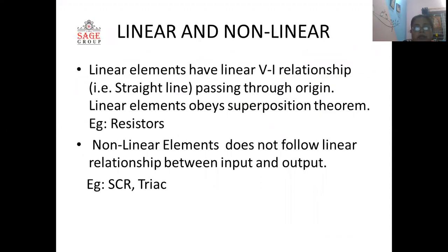Linear and non-linear. Linear elements have the same linear VI relationship, that is a straight line passing through the origin. Linear elements obey the superposition theorem, for example, resistors. Nonlinear elements do not follow a linear relationship between input and output, for example, SCR, triac.